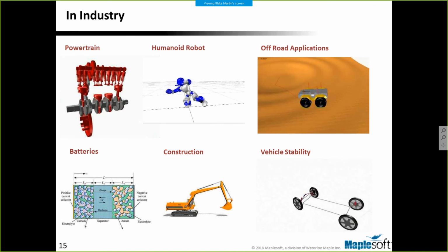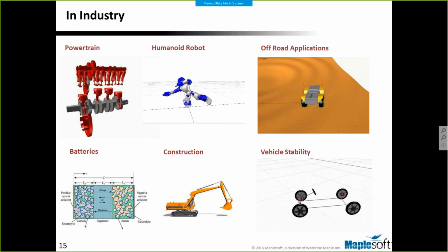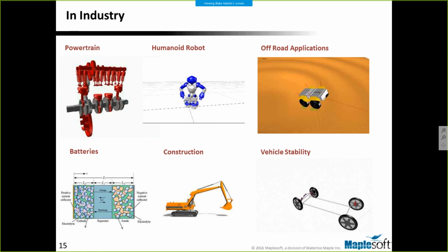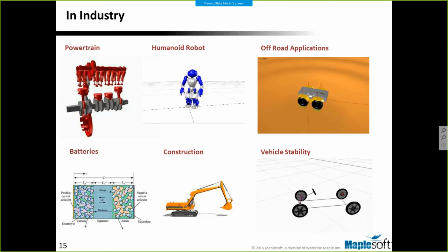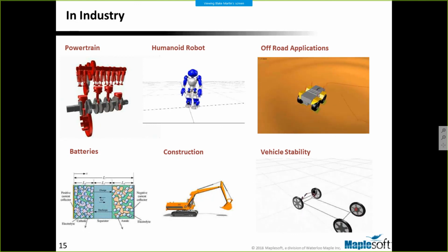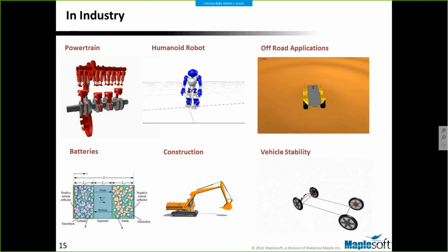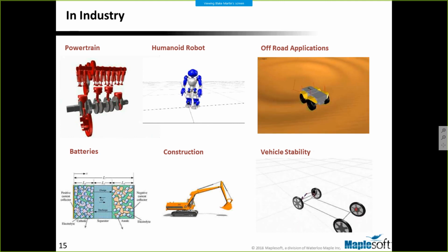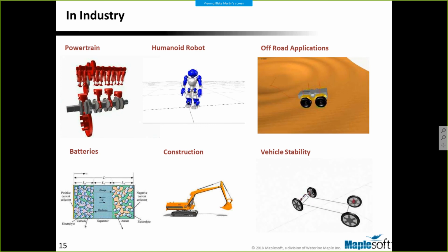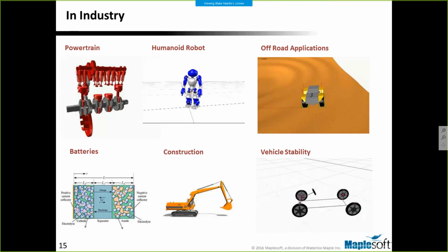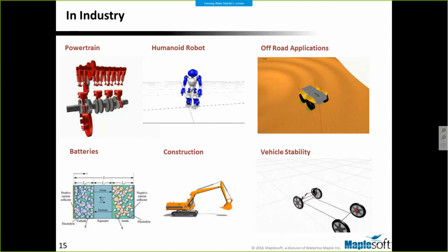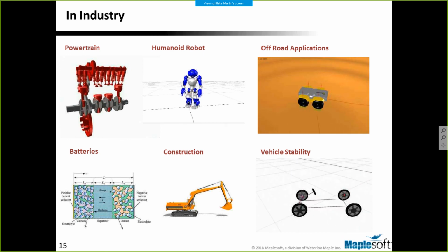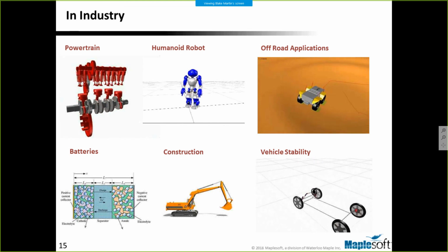We have batteries, we have a built-in library for batteries, which can be used to model lithium-ion batteries, very common batteries, and lots of the chemical behavior and the thermal behavior is going to be built into these. Another interesting aspect is, let's say, for example, you wanted to put a certain battery, but the type of battery that you want to model isn't quite there. You can use a custom component and really just define the chemistry and anything that's going on that isn't quite captured by our built-in library, and make it really unique and really your own, and really customize it towards your needs.